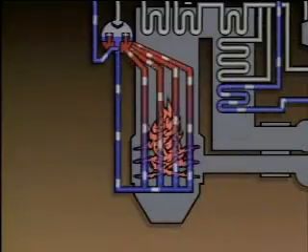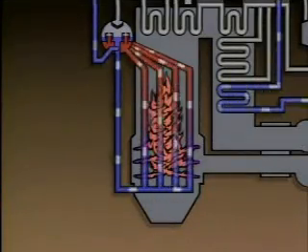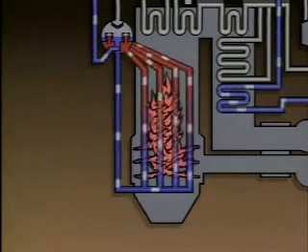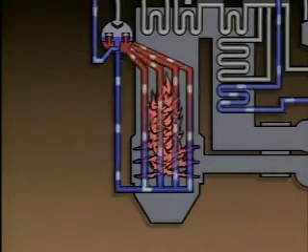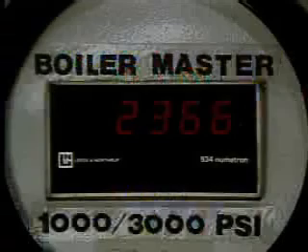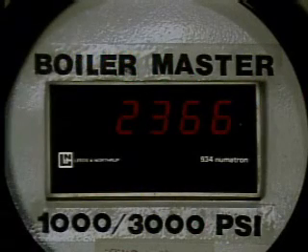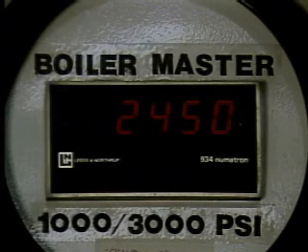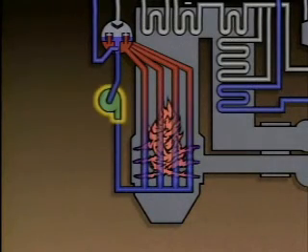Natural circulation of water in a boiler is affected by 2 factors. They are the amount of heat produced in the boiler furnace and the pressure at which the boiler operates. For example, raising the temperature in the boiler furnace increases natural water circulation because it results in a greater temperature difference between the water walls and the downcomers. Increasing the second factor, pressure, has a negative effect on natural circulation because as pressure increases, the density difference between water and steam decreases.